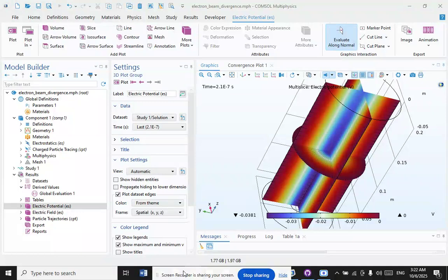Specific summarized conclusions to this simulation are as follows. The first one is the location of the beam focal point determines the penetration rate and total penetration for beam power densities that are not sufficient to always fully penetrate the substrate. The next one is that as the focal point is moved to the bottom or far face of the substrate, larger thermocapillaries are generated and more material ablation is observed.